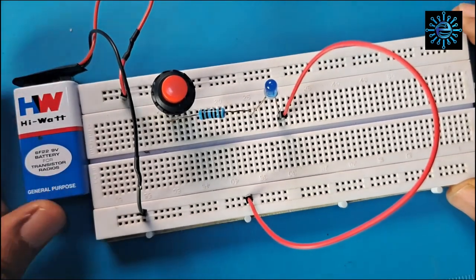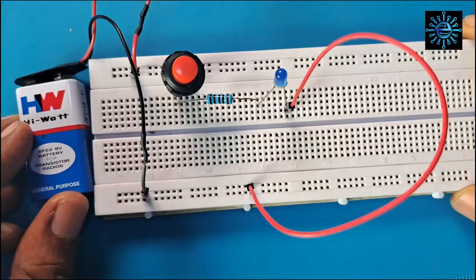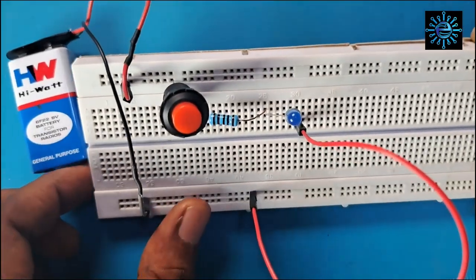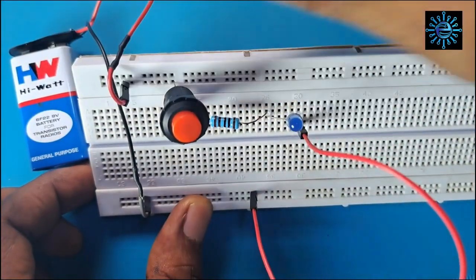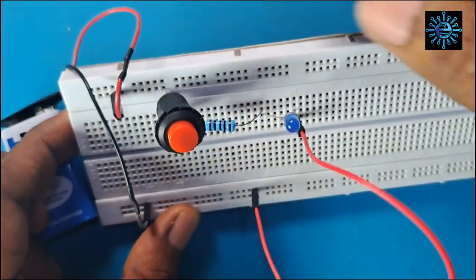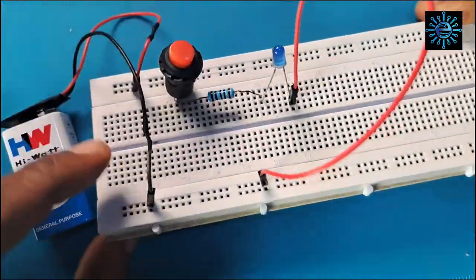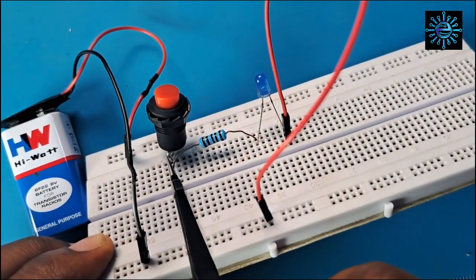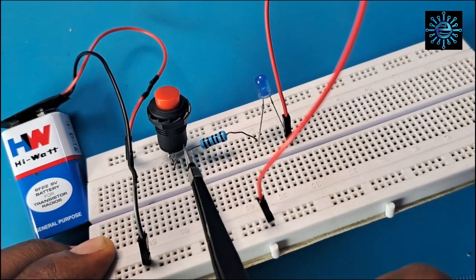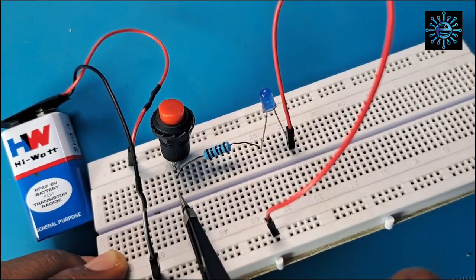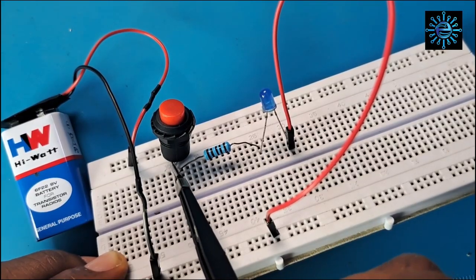On our circuit, we have the battery connected to the switch with the help of a battery cap. So the positive leg of the battery, which is this red wire, is connected to one leg of the switch, which is this leg of the switch, and the other leg of the switch is connected to one leg of the resistor. So this is the second leg of the switch. It is connected to one leg of the resistor, and the two of them are connected on this line of the breadboard. Anything connected on this line will make contact with these two legs of these two components.